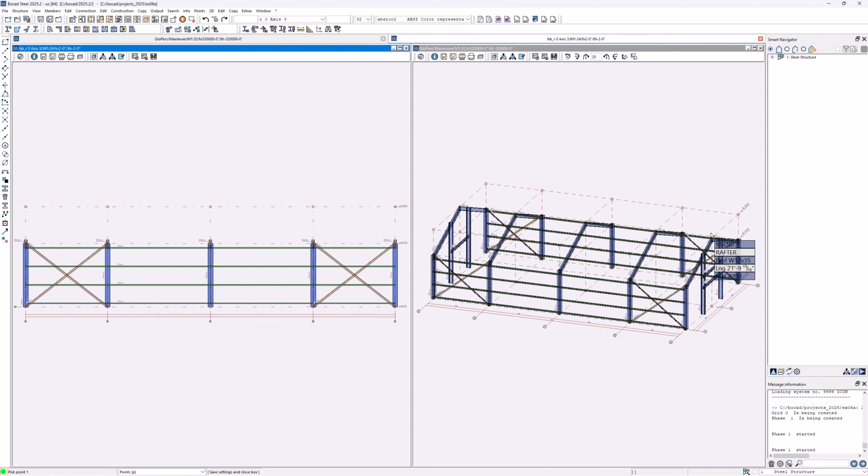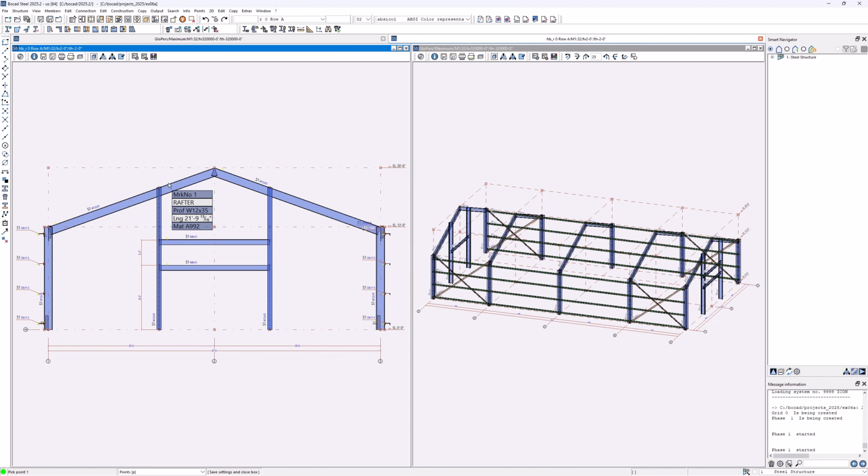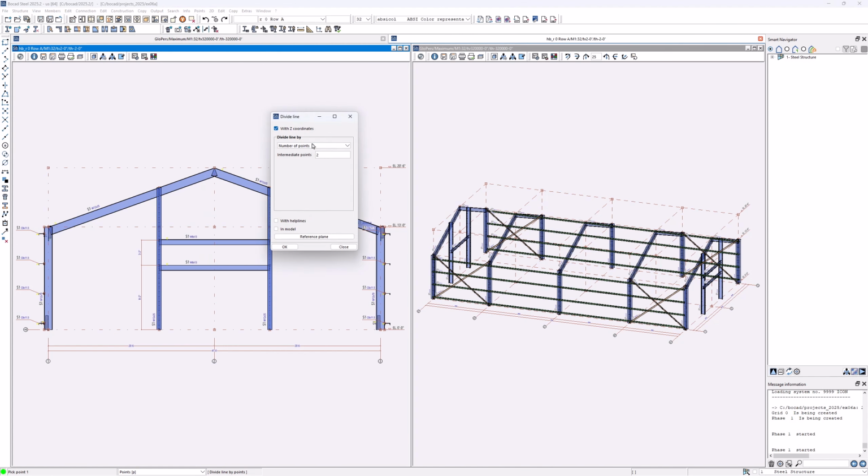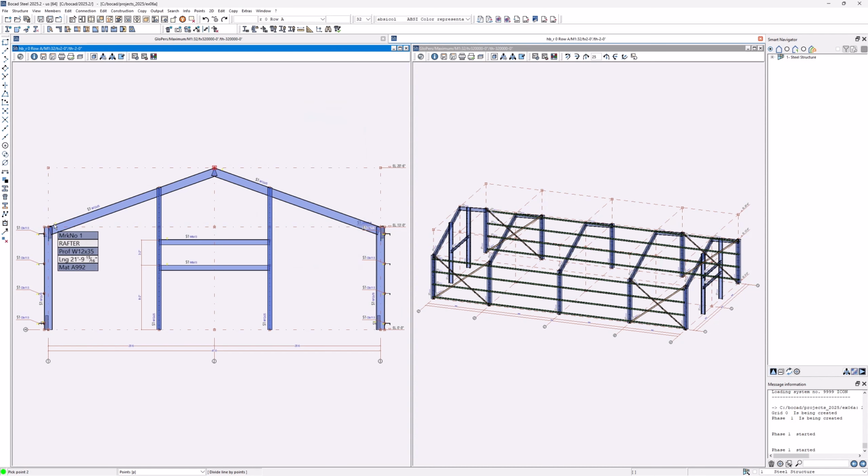Last one I would like to add for now are the purlins. Now for the purlins, I could certainly go back to row A and work in here. All I need is again an equal division, divide line, this time with rest P1, P2. 5 feet will be the fixed intermediate distance between there and there, there and there.